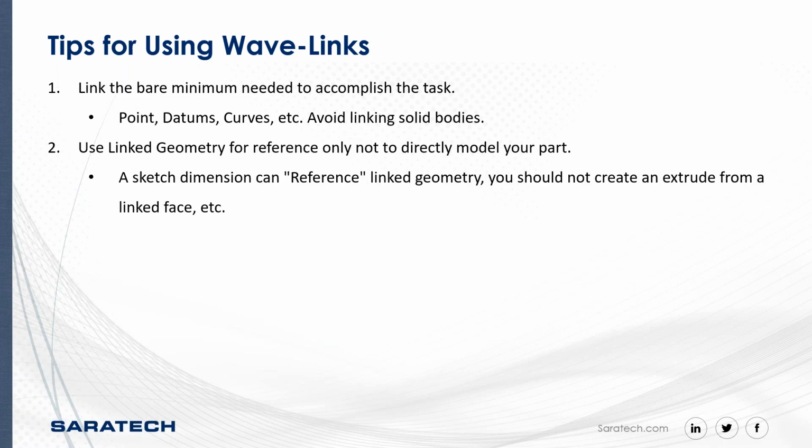Use the linked geometry for reference only, not to directly model your part. So if you're linking a curve, don't use that curve to extrude your part. Use that curve as a reference. I used the datums as references. The interpart expression, that offset, I used that as a reference. So you're not directly extruding from a linked component.